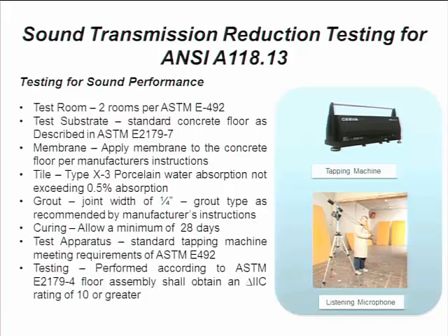Your test substrate would be a concrete floor, which is built according to ASTM standards. The membrane would be applied over the top of that concrete and the tile. And here's where we're talking about what goes into the assembly, which has an effect upon your test results. By changing what you're plugging into the assembly, you can have an impact upon your results if it varies.